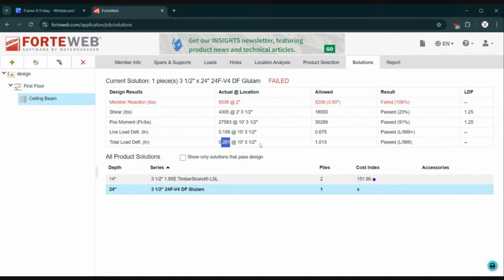That's totally fine. And here's the other cool part: glulam beams are actually cambered. So they're bowed, offset in the direction of what you're trying to load them. So when you load them, they straighten out, which is really cool. And that's just because of the manufacturing process. So that's a neat thing to know, but we're good. The beam actually is not going to fail.